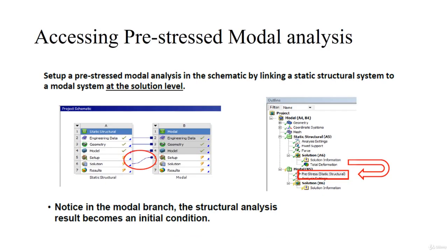In order to perform this type of pre-stressed modal analysis, first you need to perform a simple static analysis, and then bring this solution as an input to the modal analysis. Don't worry, we are going to see this example as well in the coming lectures.